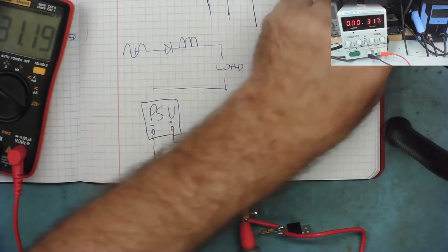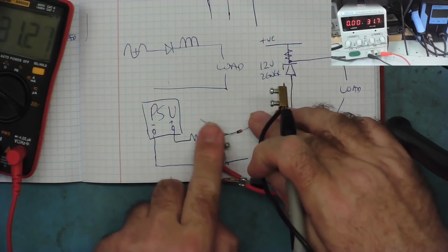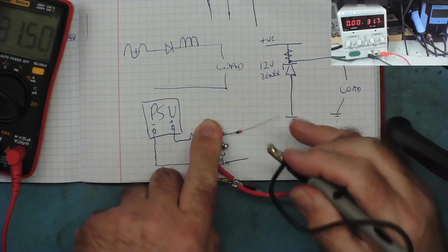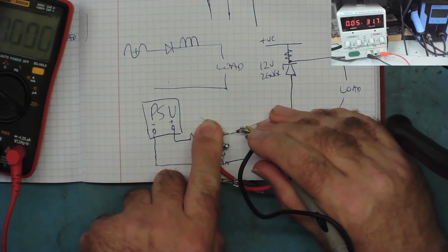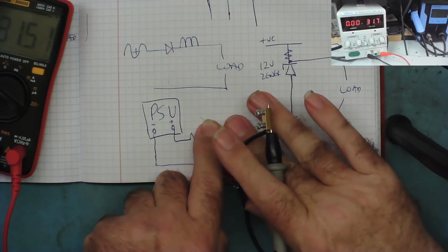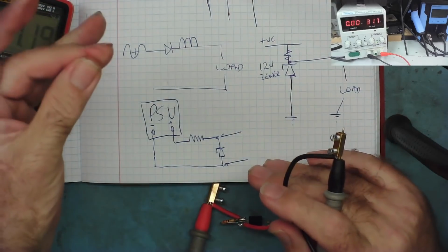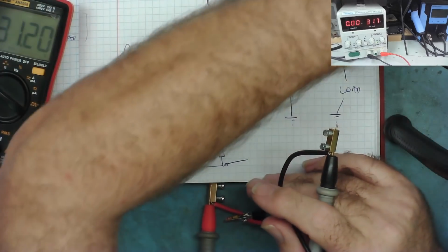And I've lost it, just get it back. There we go. Now let's test it in the Zener direction, see if it reads 2 or thereabouts, and see if it's okay. Yeah, it's reading 2.8. I'll just keep it on there a little while. It's maybe slightly warm to the touch, but it certainly was quite happy with that.